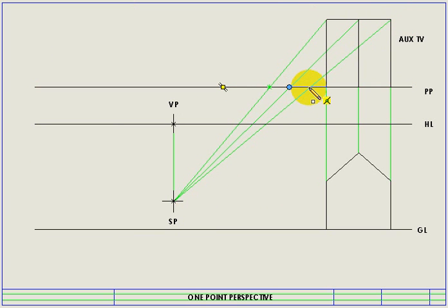A common mistake made, guys, is that people connect each one of these points that are not touching the picture plane to the stationary point, and then they want to create points on the horizon line to drop from. Please don't make that mistake. It has to happen on the picture plane, always.